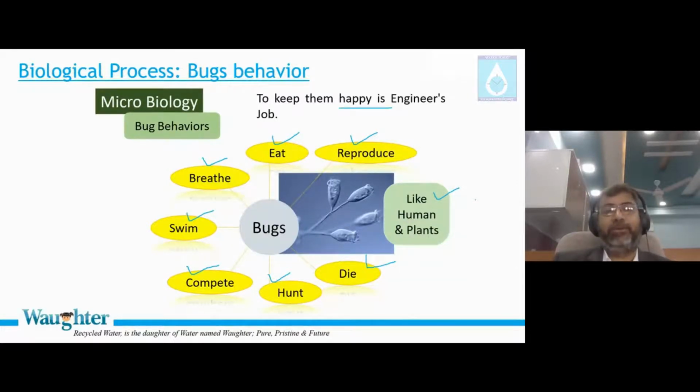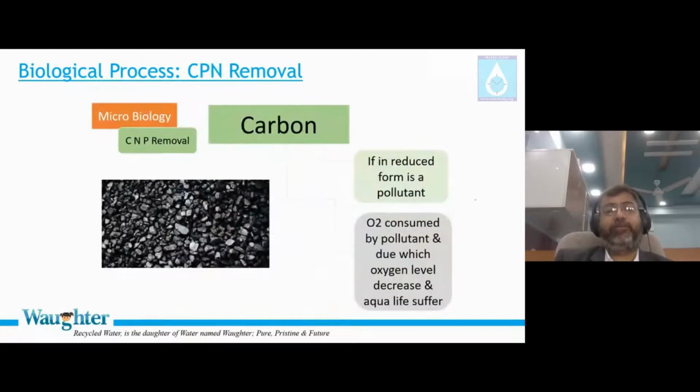In fact, on this note, some of you might be very senior in your organization, working on large-scale sewage treatment plants or wastewater treatment plant facilities. I pose a question to you: do you have microbiologists in the team? If your answer is no, please hire one as quickly as possible. Because for the health of a good sewage treatment plant, the microbiologist is an important member of your engineers' team, as he understands bug behavior. We may learn it too, but I may become a doctor, and the injection will still be given by a nurse. So there is a role for a microbiologist in the team, and one must have one in a large-scale sewage treatment plant or effluent treatment plant.